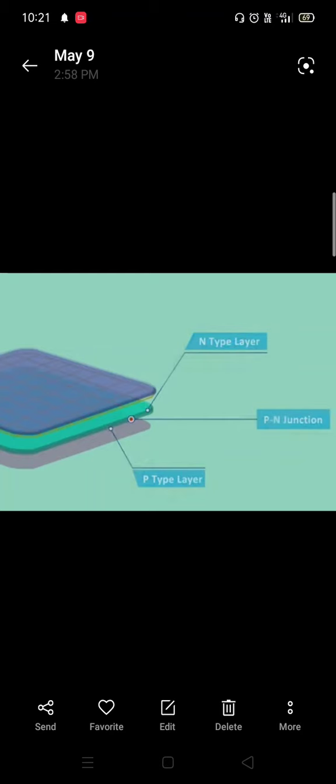So there is a negative charge layer created near the p-type region. There will be a positive charge layer, which is called a hole charge region, near the n-type material. The region of these two layers is called the depletion layer, which we call the p-n junction layer. The sunlight penetrates the top thin layer easily to reach the depletion region. Due to the charge deficiency in the depletion region, it contains neutral atoms.